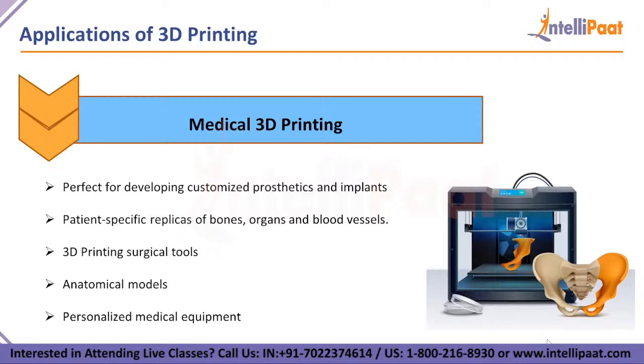For printing production parts, speed and price are also very important, but the characteristics most commonly exploited are design freedom and ease of customization. In aerospace and automotive, topology optimized structures with a high strength to weight ratio are used for high performance parts, and components that previously required assembly can be consolidated into a single part.